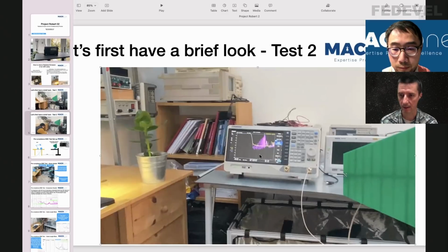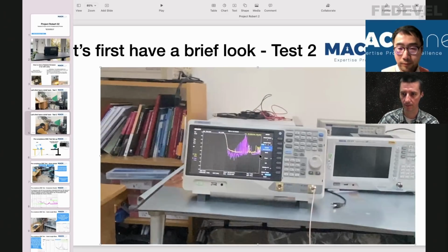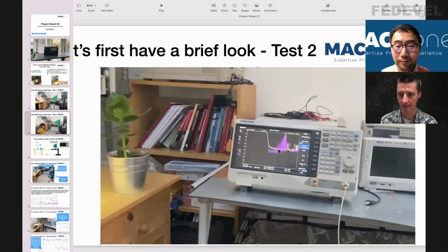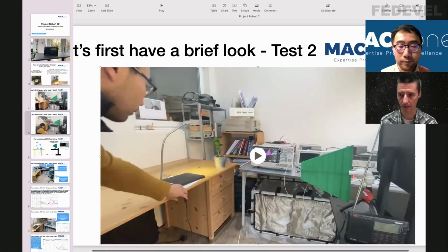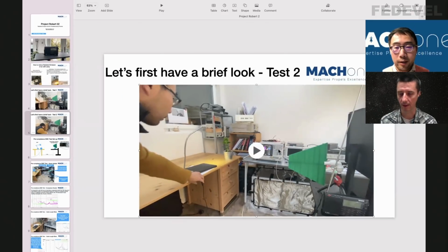Okay, now we can see the purple, and that's the noise the lamp is making. You can see the spectrum was pushing high, and the radio station has been heavily affected. Basically, the music you listen to has all the noise. So what is the next step? We know there is something wrong with the lamp. What are we going to do next?